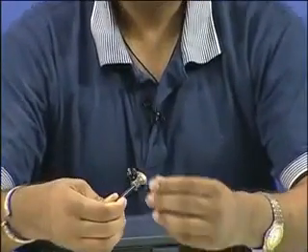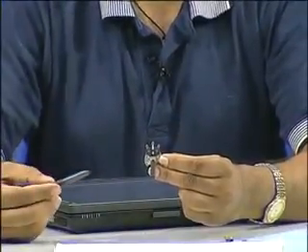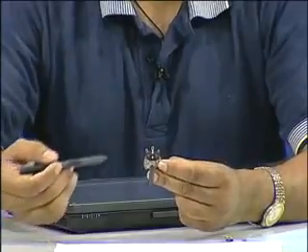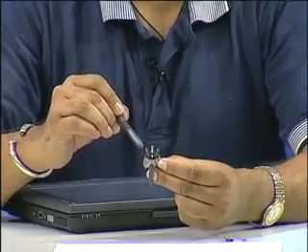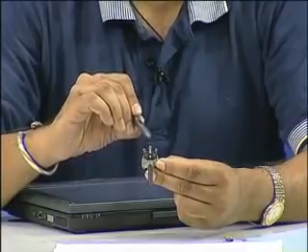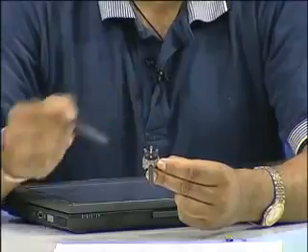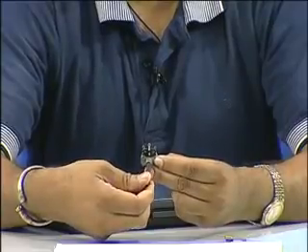Apart from these resistors, there are other resistors which are bigger in size to handle higher wattages. Now, here is one such component. This is also a potentiometer, similar to the low wattage blue box that you saw previously. This also has 3 terminals. These 2 are the extreme terminals of the resistor, and this center terminal is the center tap, which will vary with respect to the end terminals. And the variation of the center tap can be attained by rotating this vertical knob, which is around here.